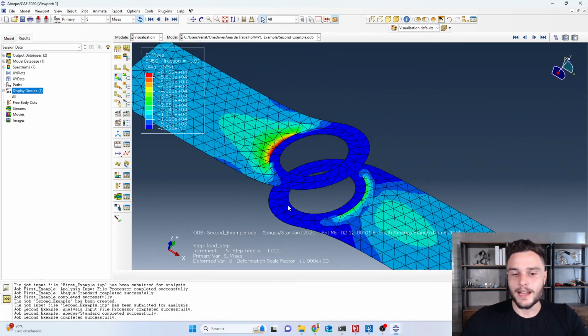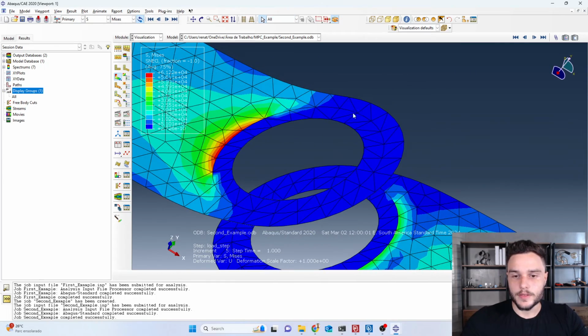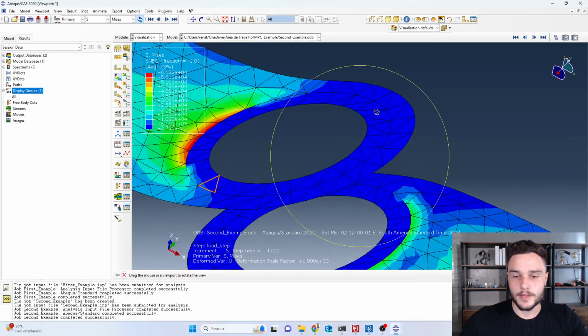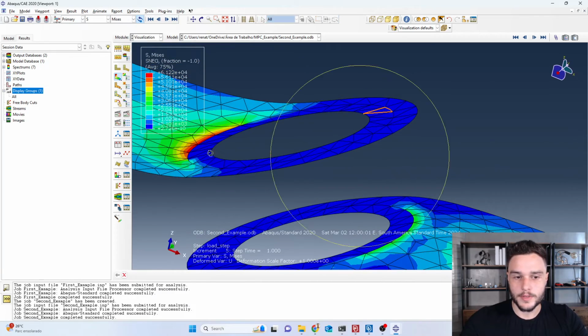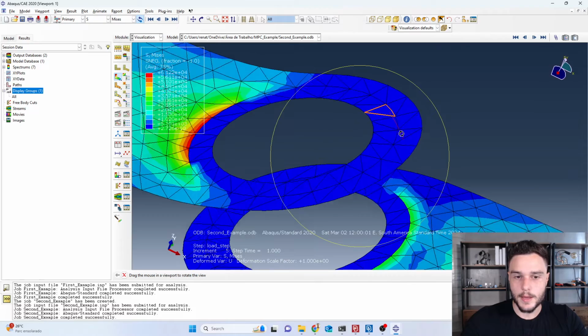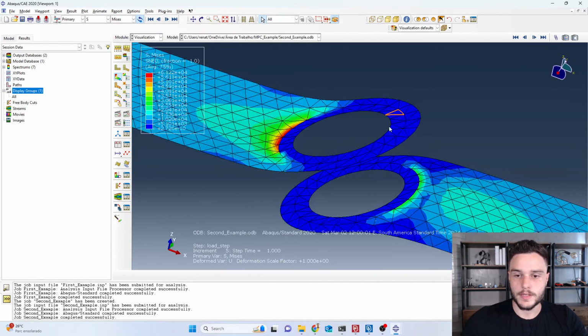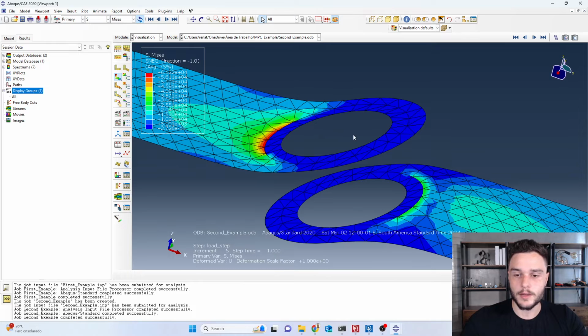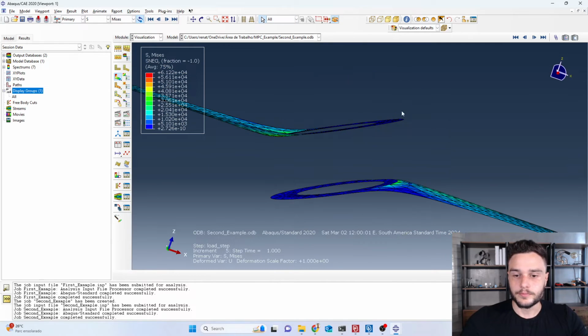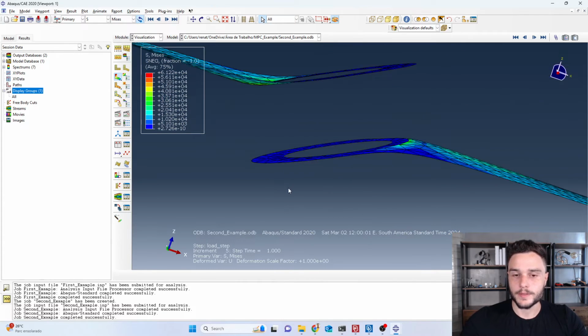And you see that now the surface where we have used to define the coupling, since this is a kinematic coupling, now this surface is rigid. So that means that it doesn't deform. It just rotates as a rigid body. And the same thing happens to this surface.